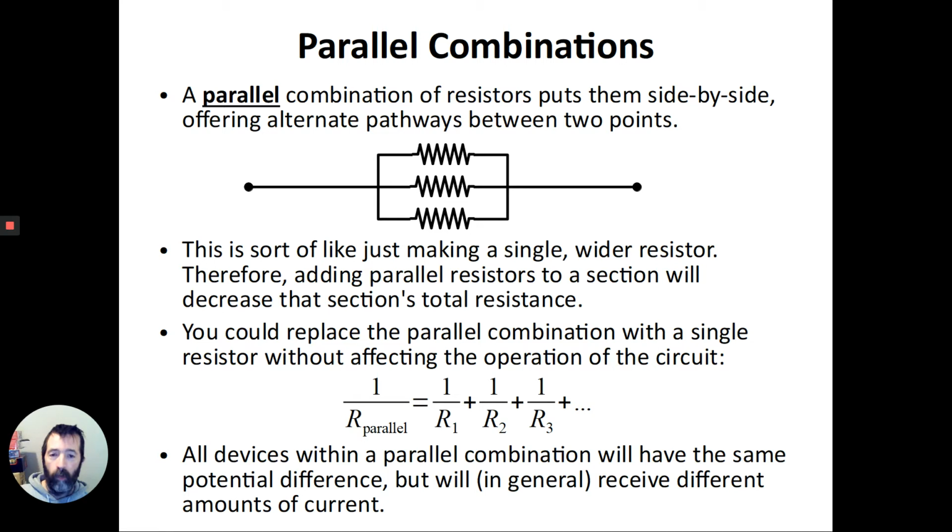So if you want to mathematically add together the effect of parallel resistors, it works out to be this weird thing with reciprocals. This is again related to the fact that the cross-sectional area was in the denominator of that resistance formula. And the book goes through the whole process of deriving this form. I don't want to talk through it. It's not the kind of thing that you want to listen to someone talk about. If you're interested, you can find the derivation in the book.